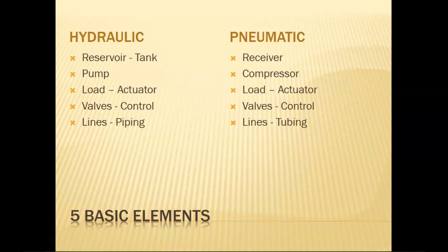You have to have a pump. What does the pump do? It takes the oil from the reservoir and moves it into the system, because otherwise it just sits there. Okay? You have to have some form of a load. Normally it's called the actuator. It's great to have a system and all, but if you don't have anything doing work, what is the point? You have valves that help you with the control of it. It helps direct it and move it so that you can do more things with that circuit. And then you have to have some form of piping. Generally with hydraulics, you want it to be very well sealed because we don't like leaks in hydraulics. Why? Because A, hydraulic fluid's expensive, and B, it can be flammable. You don't want that in places that it does not belong.